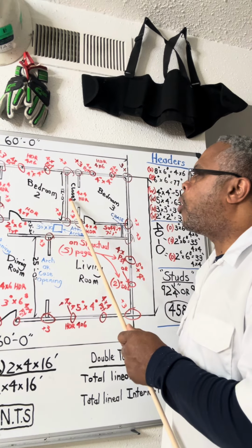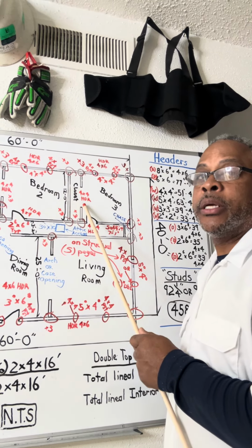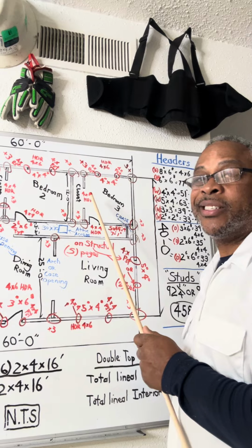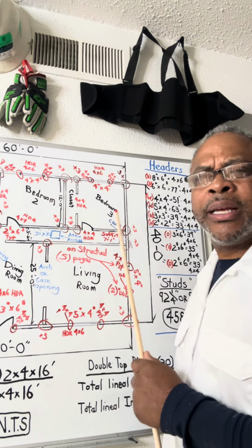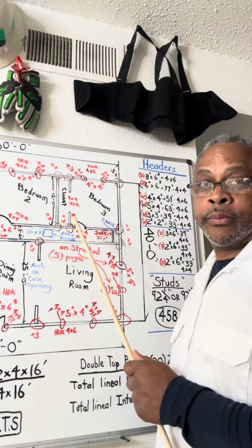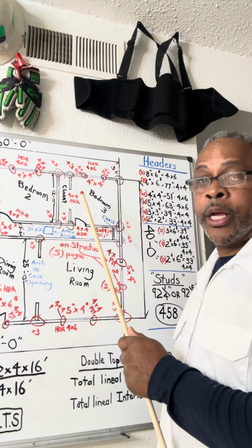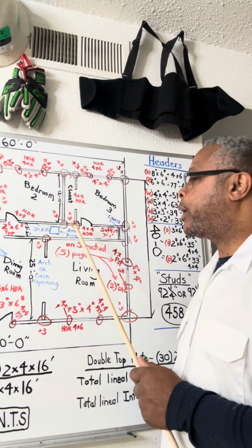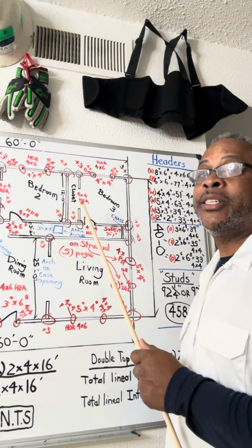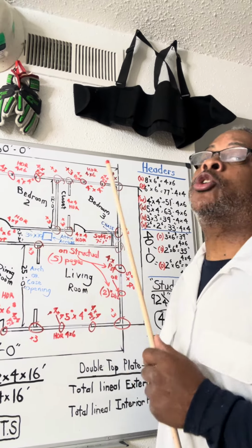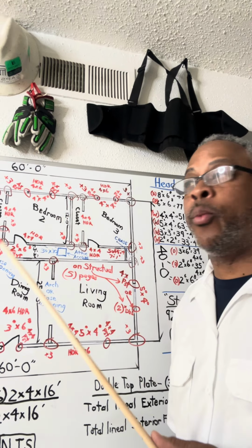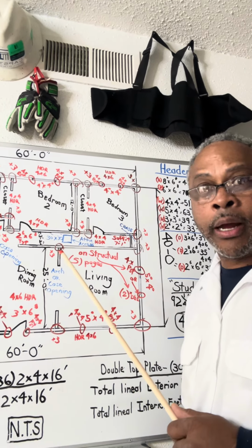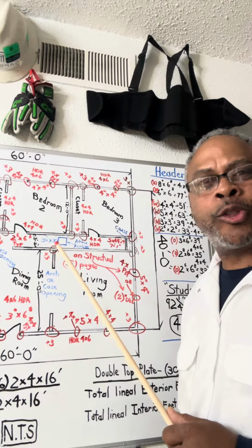Between this wall and this wall here, it's going to be 30 studs, 15 and 15. Well, why? Can't you just take some? Look, you've got cripples to cut for this wall. You're going to have blocks that you're going to need for your channels. But there's going to be scrap that you're going to need, because this lumber is going to come in handy for when the plumber comes in and butchers up stuff. You've got lumber, so don't worry about it.